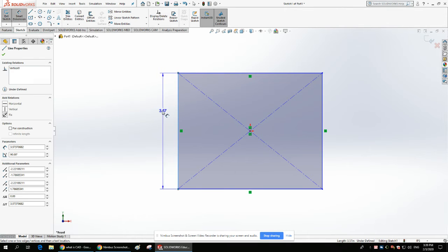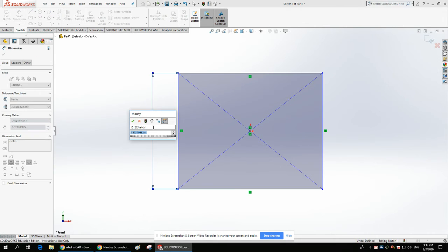I'm going to click here, and I'm going to put my dimension. Now, most times style-wise, you can put this anywhere you want, but it's good style to go out away from the piece, maybe a few centimeters, and it's good style to put the actual numbers somewhere in the middle. I'm just dragging around, but somewhere in the middle, a little bit off the piece, and I click.